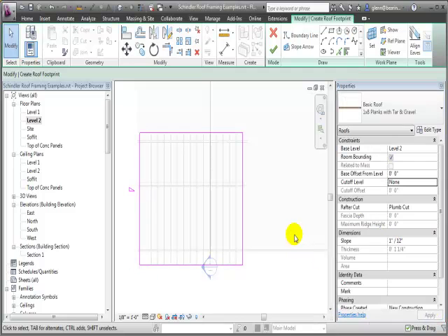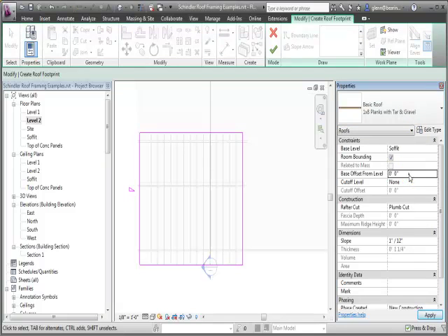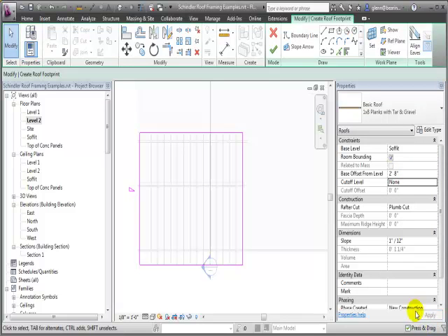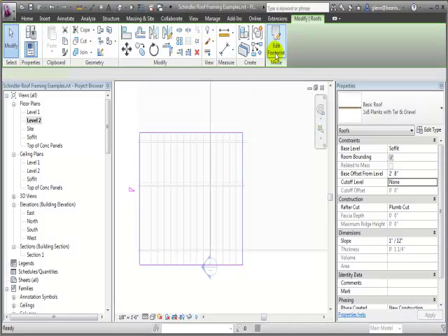Okay. In terms of the height of this roof, again, it can be the 1x8 planks. That's still appropriate with the tar and gravel on the top. It's not going to be at level 2. Really, this was going to be at sort of soffit, starting about 2'8" above, and then sloping from there. Okay, let's give that a try and see what this looks like.